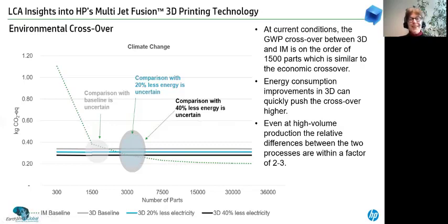And so until you've got impacts of the mold amortized across enough products, it's dominating these impacts. And you'll see that this starts to flatten out as the impacts of the mold go down to essentially nothing per part. You'll see that we have the 3D printing process as it exists today, pretty stable across all the different volumes of parts.